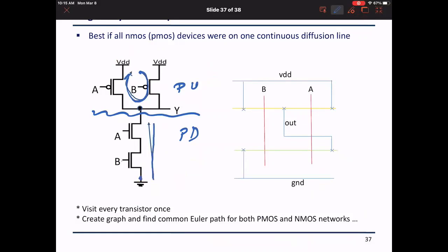And if this path bears the same name, B A, then it will allow me to simply draw a P diffusion stretch and an N diffusion stretch, and then I will follow the node labeling to connect the different nodes. First B goes to ground, then there's a common node between A and B. I don't do anything, it is connected, then I have the output.